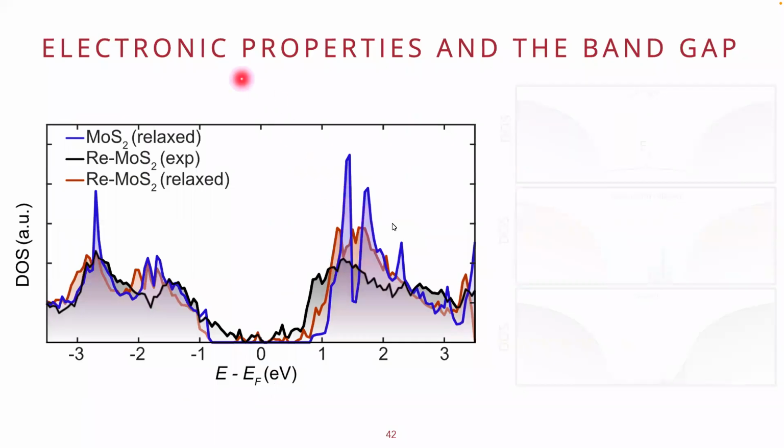So this is a graphic of density of states. In the blue curve, we see a pure moly disulfide area with a nice pristine band gap. Whereas the red curve shows theoretically what we would get in those same areas if we were to have a relaxed, 0 Kelvin pristine structure, meaning that we still get a decent band gap and we have a few defect states.